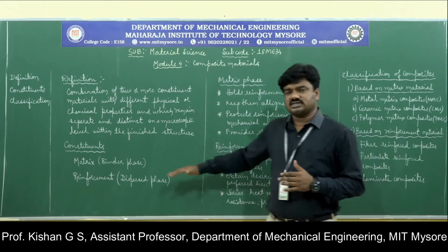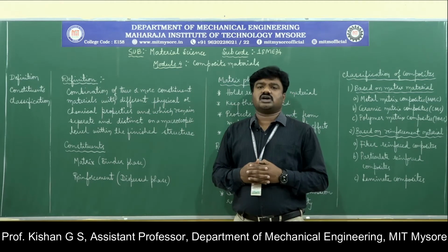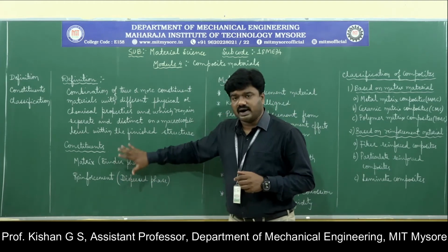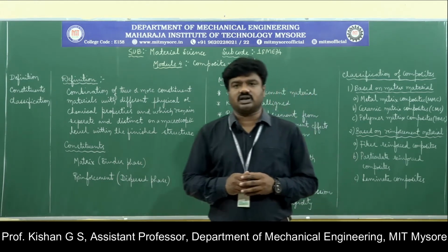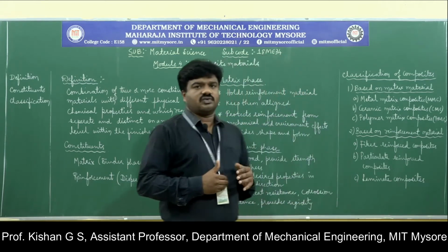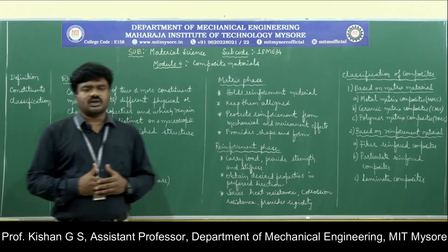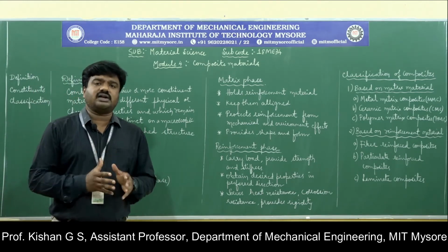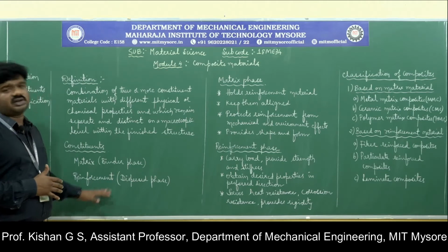The matrix phase is the phase of a material in the composite that binds together the material available in the dispersed phase. That is to say, the matrix phase binds together the reinforcement that is accountable in the formation of the composite material. We do have specific roles and responsibilities of the matrix as well as the reinforcement phase. We can look at them one after the other so that we get clarity. Keep in mind, the matrix phase binds together the particles or the phase in which the material is dispersed, and that dispersed phase is nothing but the reinforcement.